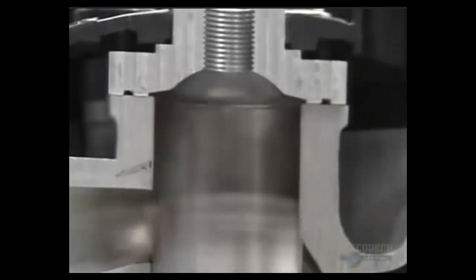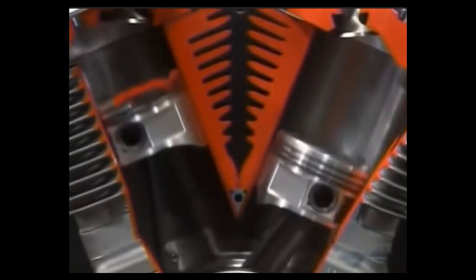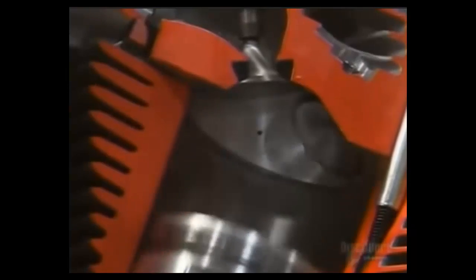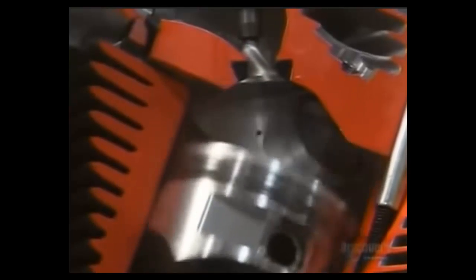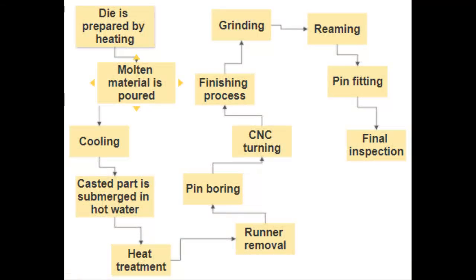Inside of engine blocks, we can also find pistons, which have an up and down movement provided by a crankshaft, synchronized with the camshaft to let gasoline and oxygen inside the cylinders and produce a combustion with the compression caused by the piston and a spark provided by the plug. Pistons can be made by die casting. This process uses a permanent mold which allows repeatability and high precision, which is important to reduce friction between the pistons and the cylinder walls.